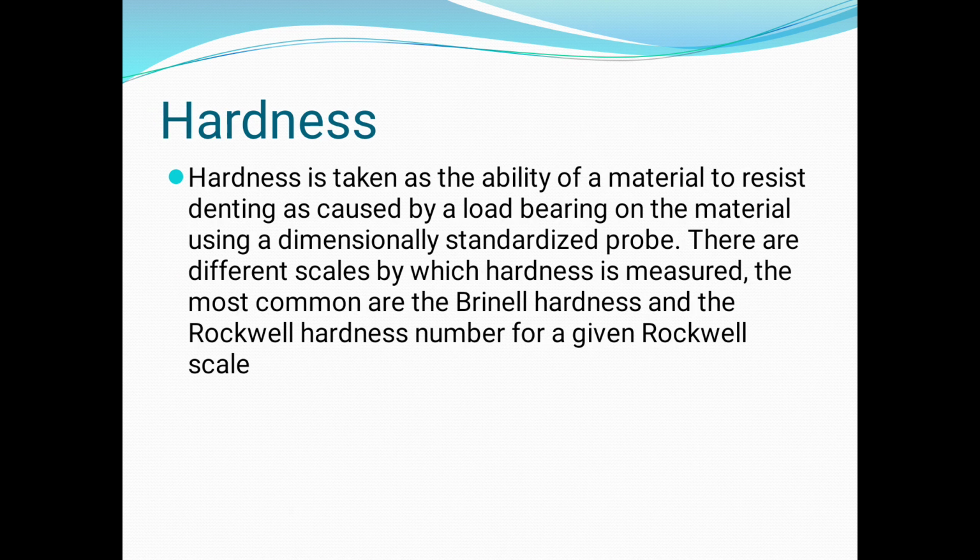And then hardness. Hardness is the ability of a material to resist denting as caused by a load bearing on the material using a dimensionally standard probe. There are different scales by which hardness is measured. The most common methods are Brinell hardness and Rockwell hardness.